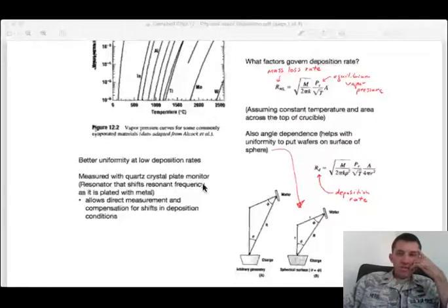So I mentioned that you heat up the metal. Well, how do you do that? The simple way is to just use a resistive heater. So that would be, say, some metal filament. Tungsten is a good choice, very high melting point. So you drive a current through a tungsten wire. Inside of that wire, right, you place a rod of whatever metal you want to evaporate. And the wire gets very hot, conducts that heat to the source metal, and evaporates those atoms.